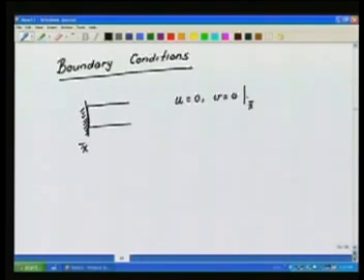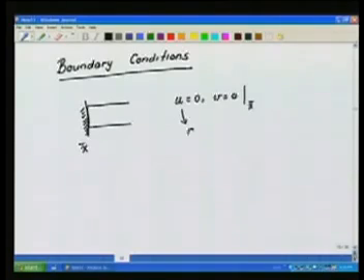Now u, by its representation, it means that through the depth, through the height it is 0, which means that this will give me dv dx is equal to 0, because u0 was 0 for our problem the way we have done it. Okay. So u becomes equal to minus y dv dx. Now for all y this has to be 0, so dv dx is 0.